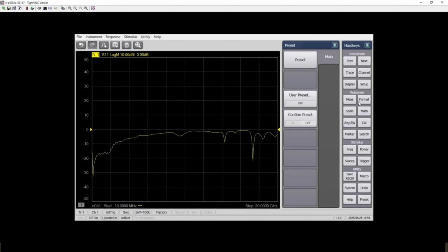In this video, I'm going to show you how you can combine all this into one view, and from there you can just plug in your device under test. In my case, it's an amplifier. Calibrate one time and you are good to go to run all the measurements in one go. I will start with S-parameter measurements.